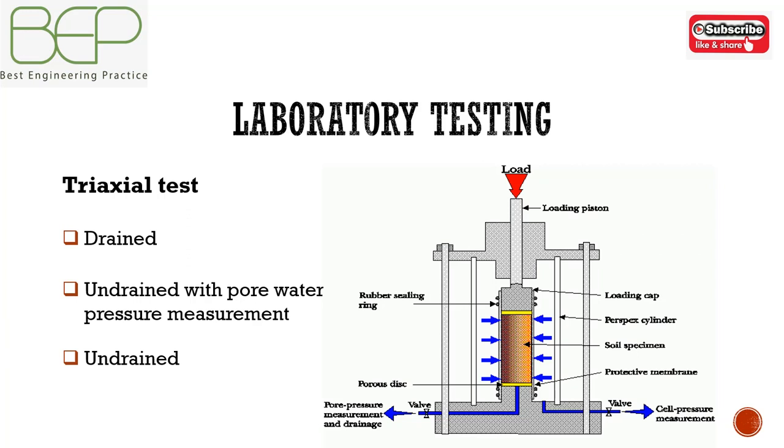Or undrained, where the vent is closed during shear, pore pressure is not measured and the test is interpreted in terms of total stress. Drained tests and undrained tests with pore water pressure are known as effective stress triaxial tests and are routinely used to measure the effective strength parameters c' and φ' of clays. The third type of test is used to determine the undrained shear strength of the soil, which is useful for design of structures for short-term conditions.